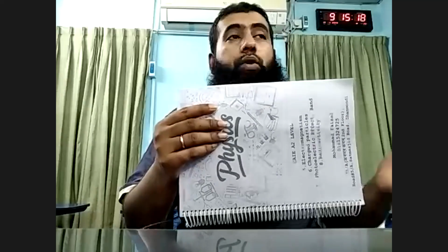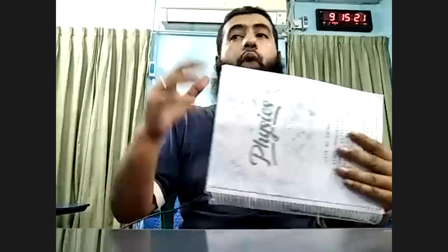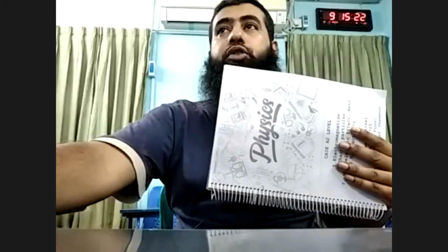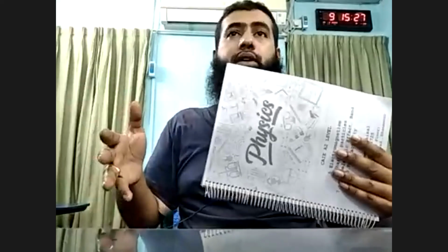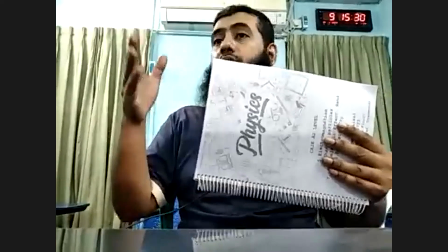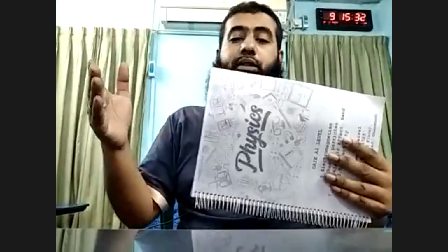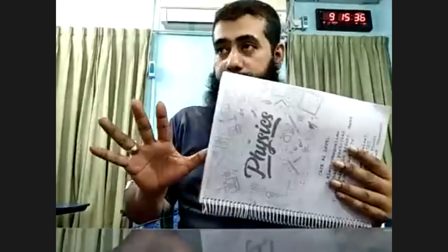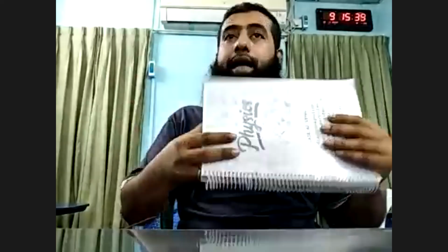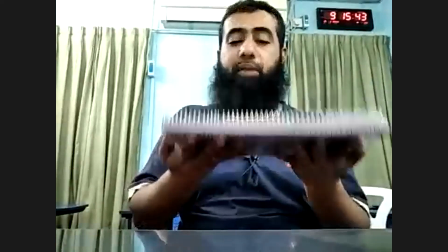So what is important, if we want to use this formula that I showed you in MS Paint a bit earlier, is that by trial and error, we have to align our Hall probe material, or in this case, what I call the metal strip, in such a way that it is placed absolutely perpendicular to the magnetic field lines.